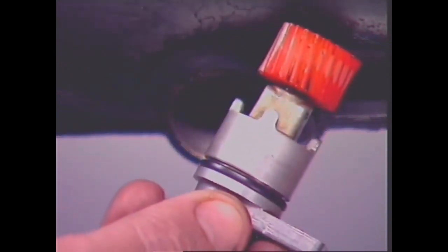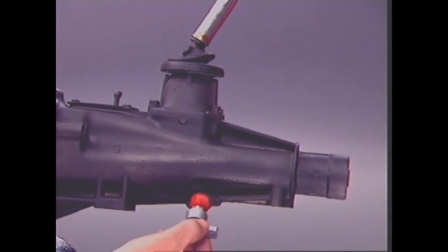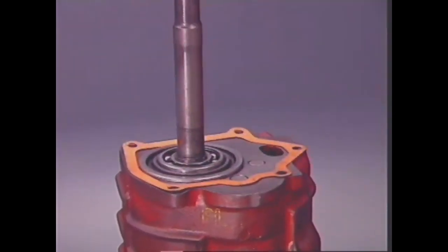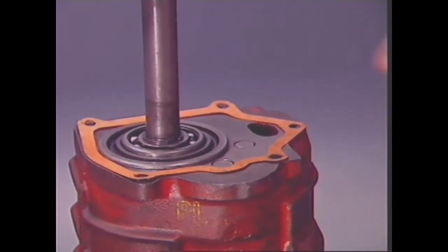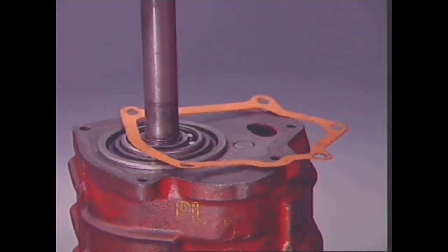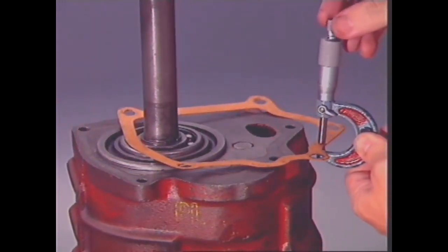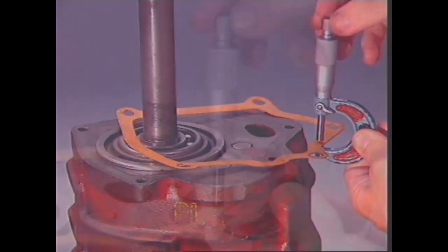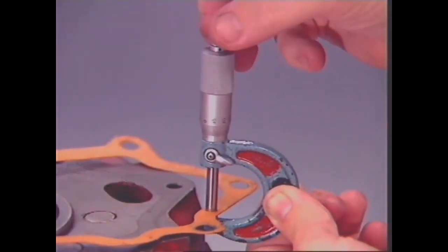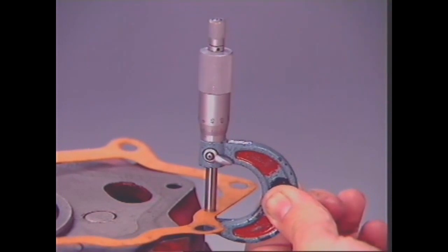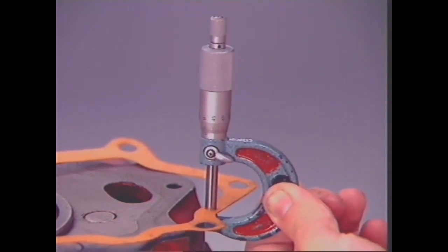O-ring type seals are mostly used for static locations, such as the speedometer drive gear housing, while gaskets are used to seal the mating surfaces between the casing and retaining plates or housings. In some cases, the gaskets may be used as selective thickness shims or spacers in addition to their sealing function.